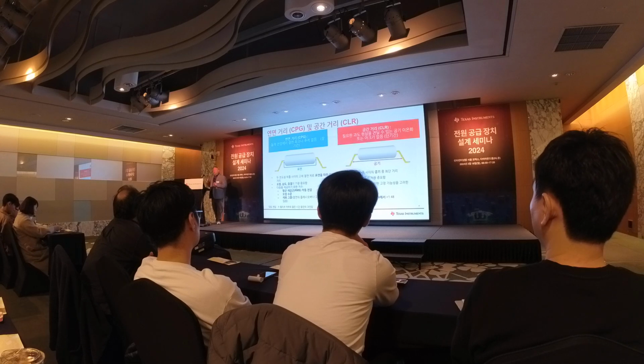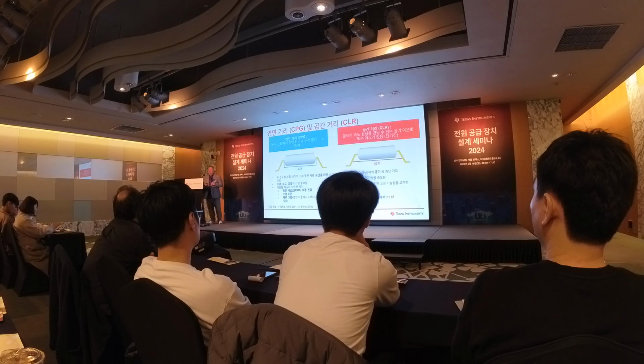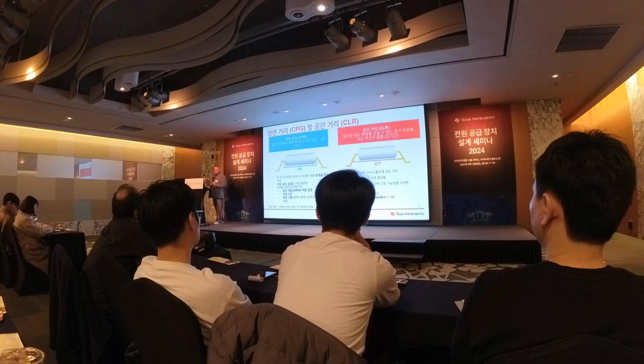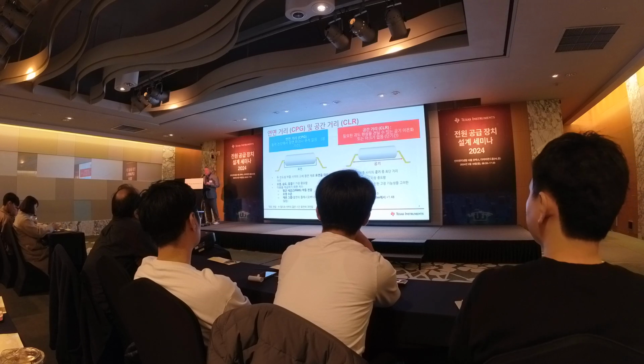We will talk about all three of these and how they relate back to the creepage distance. For clearance, the most important parameters are the transient overvoltage, the pollution degree, and the altitude. So if you're at different altitudes, then the distance needs to be accounted for differently because the air will ionize differently with a high voltage.